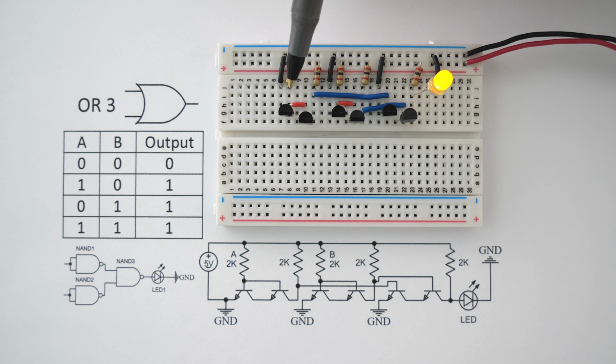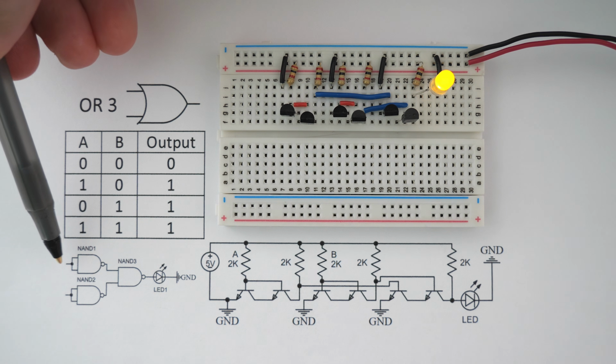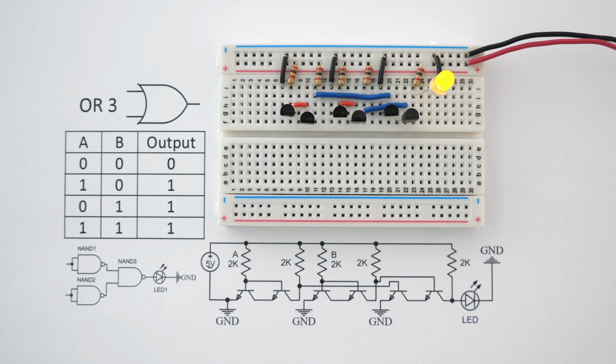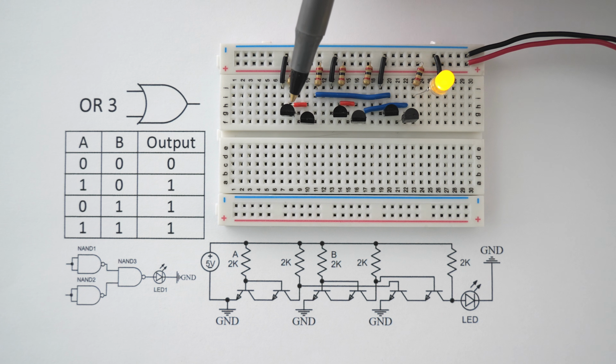This NAND gate actually has both inputs of the NAND gate connected via this red jumper, and so does this NAND gate. And if we look at how it's supposed to be built, that is how it is supposed to be built. So with this input being turned on, this NAND gate is actually turned off. It's turned off because all of the current from this positive 5-volt rail is going to flow across these transistors and into this ground rather than go into the output. And the same is true with this NAND gate.